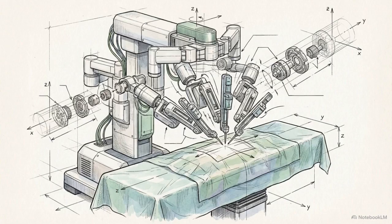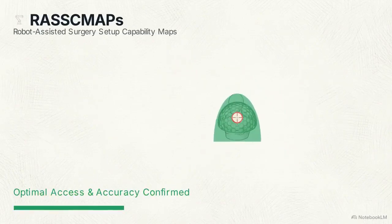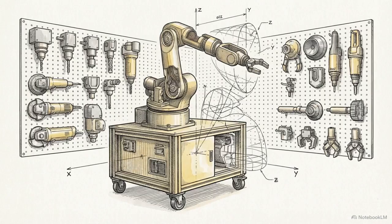Other applications reverse this priority. In surgical robotics, throughput and speed are irrelevant compared to absolute reachability and strict positional accuracy. Engineers map the surgical space using preoperative robot capability maps, or RASC maps. These models optimize the base pose and access points entirely for guaranteed millimeter-perfect access, explicitly trading velocity for safety. A robot's speed-to-precision ratio is a deliberate choice hard-coded into its controller architecture, an intentional configuration rather than a mechanical byproduct.